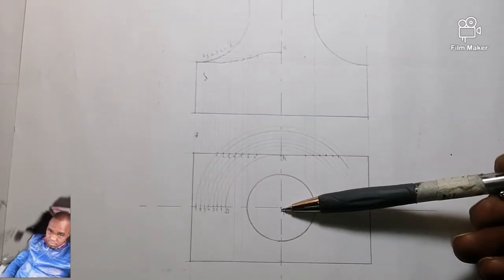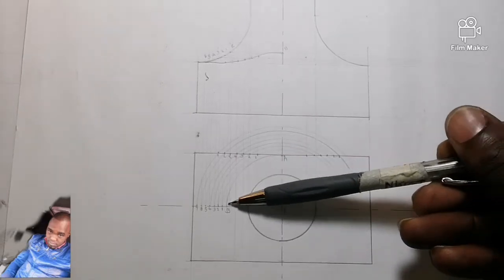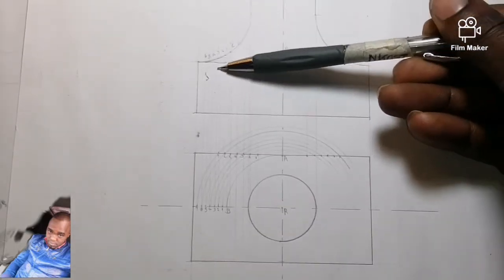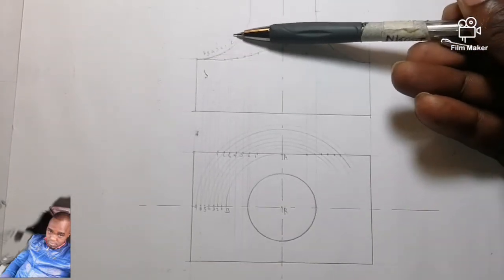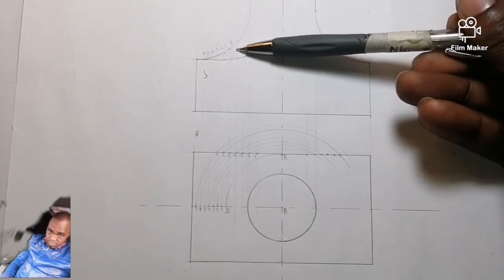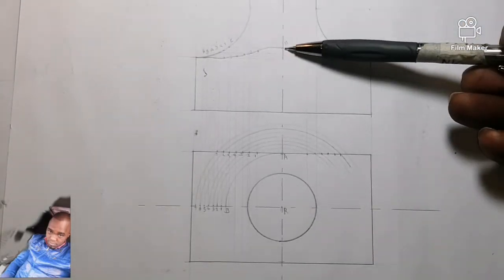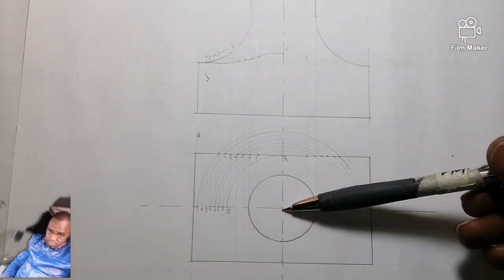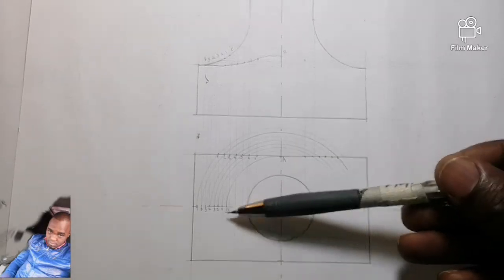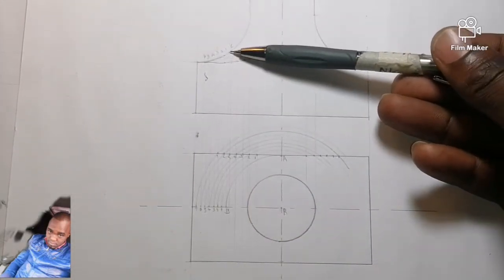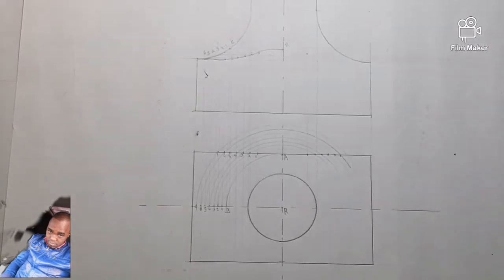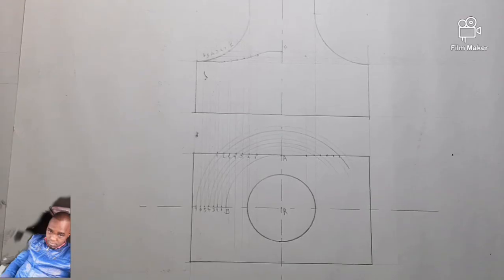So we place our compass at R, further extend it to A to get B. Then from there you go up to your front view. Once it touches that arc of yours, it is going to give you point C. Then you take it horizontally to give you point H. Let me repeat that. We've got R and A, B, C, then C to give you your highest point, which is H, standing for height. So you can number this according to your preference, but your numbering has to be constant.